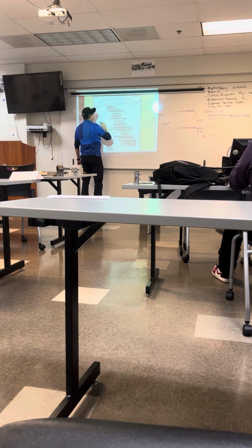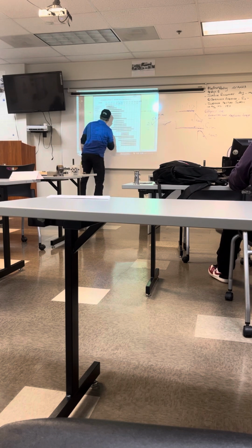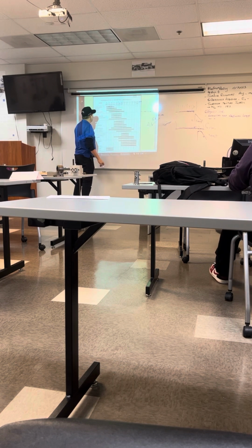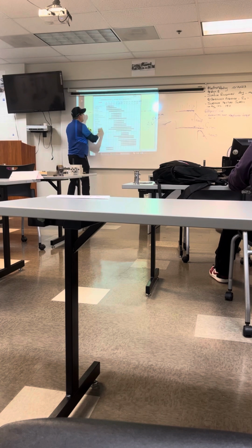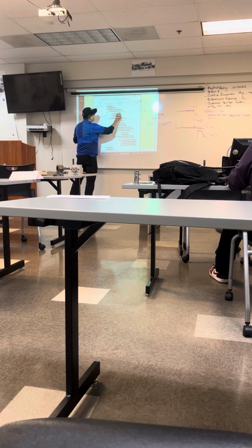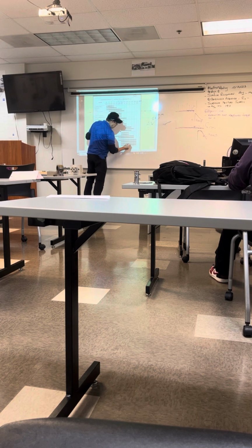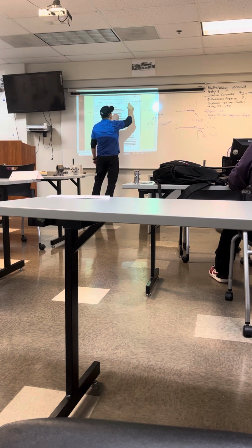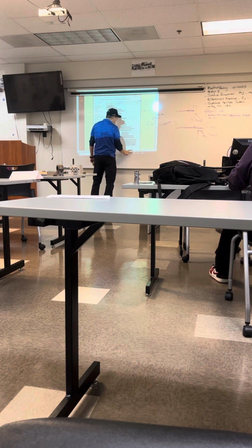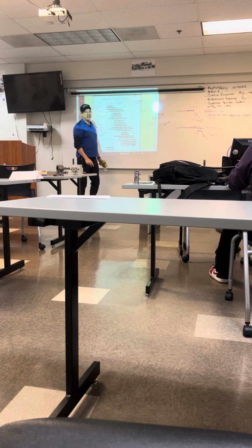Plain cutting is 500 micro inches, which is almost 5,000 roughness. But if you go to chemical milling, they start getting better surface finish. And then if you have lapping, electropolishing, super finishing, you notice that we have more finishing, up to what? 4 millionths, 8 millionths, 16 millionths. That's super finish. Does that make sense?